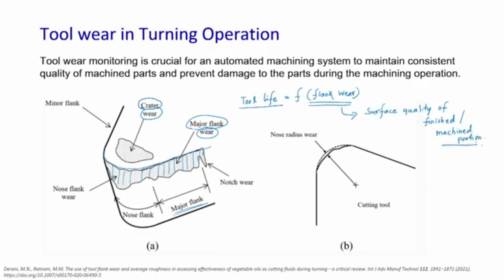Fine. So, now how the lasers can help us to find out the tool life. We have to go in a reverse way. Can we find out the surface quality, in situ, in-process surface quality measurement by using some laser based technique, which will give us the flank wear values, and those flank wear values can help us to find out the tool life.